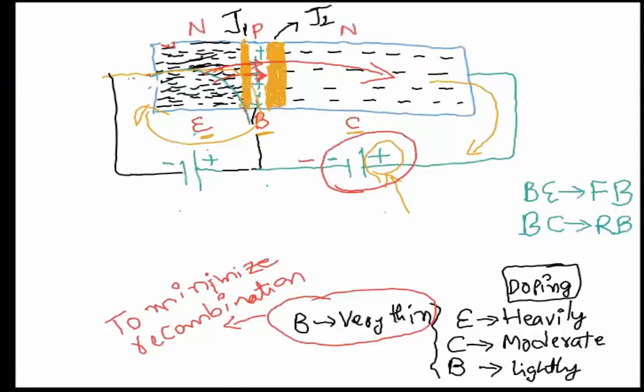because all these electrons now pushed into the p-type will repel, which will push the electrons that stick in the base all the way to the collector region. That's from the majority carrier's perspective on how to overcome the barrier under reverse bias between base and collector. So that's how the majority carriers work. In this case, we are purely talking about the electrons on either side of the n-type material.